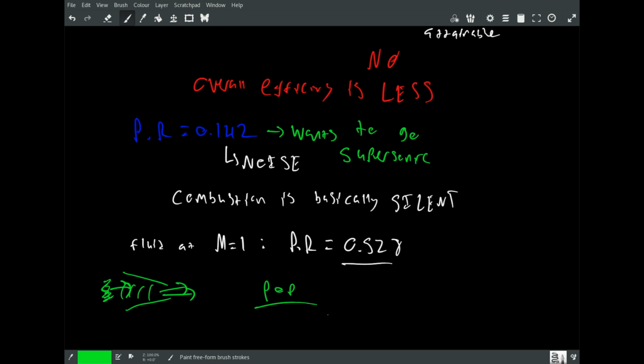So that's an interesting point with regards to this pressure ratio. That's more what you're hearing. You're hearing the air exiting the cylinder, the air exiting into the muffler. You're not so much hearing actual combustion. That's not what's making the noise in the engine. If you have an older car, perhaps you're hearing some belts slipping as well, or perhaps you're hearing some other noises as your car breaks down slowly. But that's essentially what that noise is.